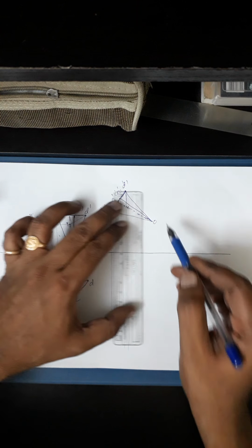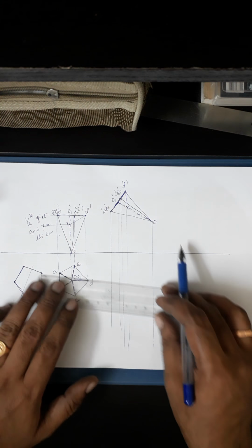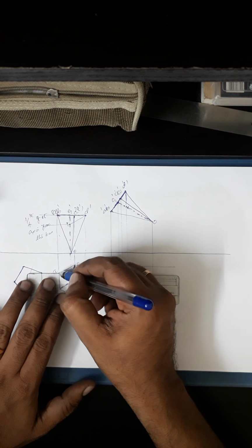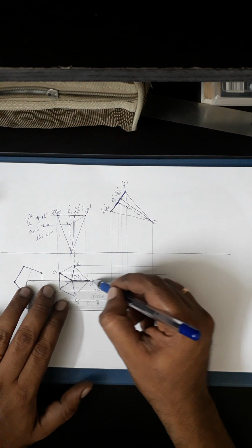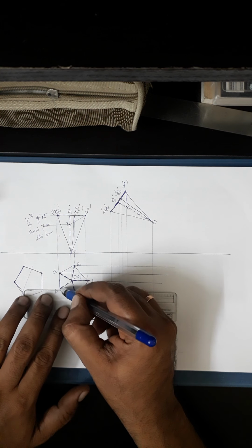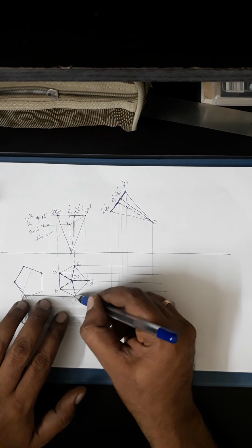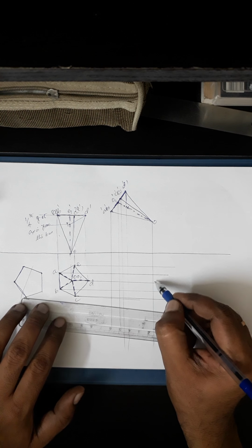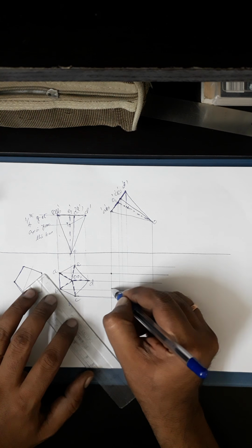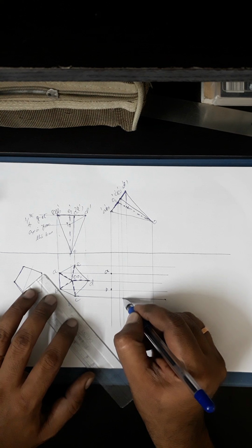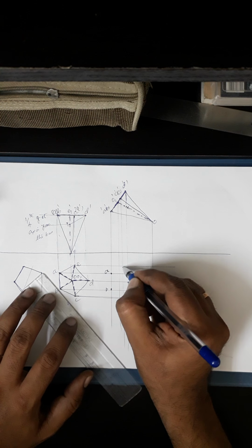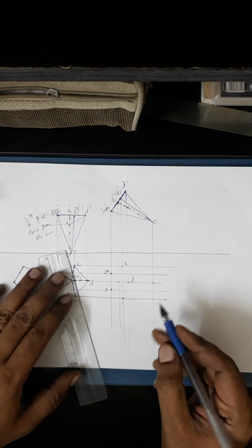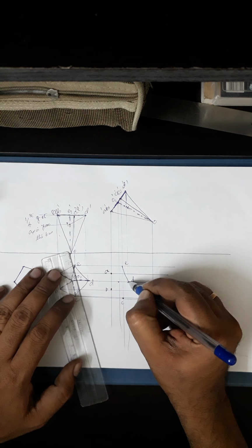It will be the apparent length. Unless they specify that particular three sentences, that the axis appears to be inclined, or the projection of the axis on HP, or the top view of the axis inclined to VP, or the plane containing that edge or something like that. If they don't mention it, then because the axis will be apparent, the given angle what they give in the problem